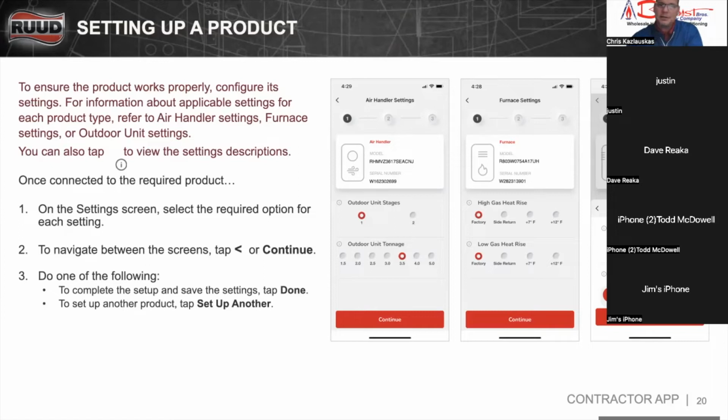So just like in this air handler, we're going to tell it, hey, here's our model number, here's our serial number. We're going to tell it outdoor unit stages. We have 1 or 2, what tonnage. We get into all that information there. On a furnace, you have your high gas heat rise that you can set. Recommend you just keep it at factory, but you can do some customization if you need to, that kind of stuff.